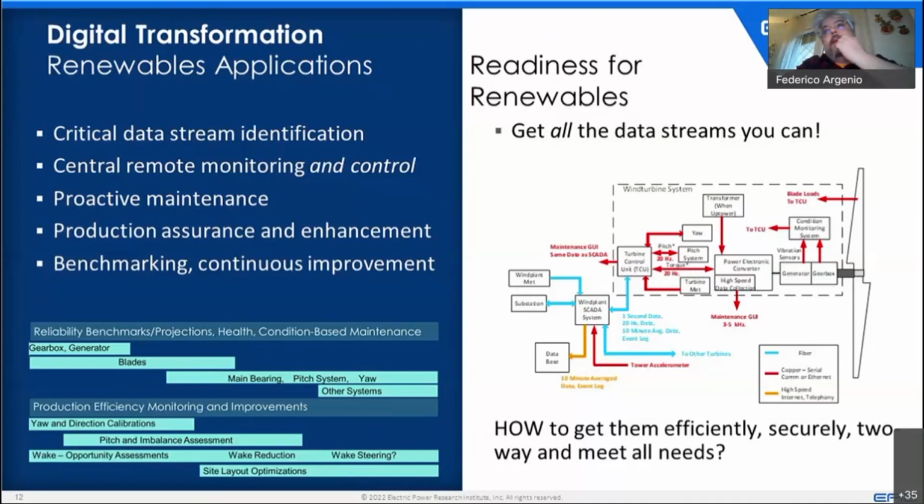We check the coherence of the different data, because a problem of these sensors, especially if you have a problem in terms of voltage and stuff like this, is that they can stop and send you the same value consecutively. We call this frozen data. So we have a detector for frozen data and so on.